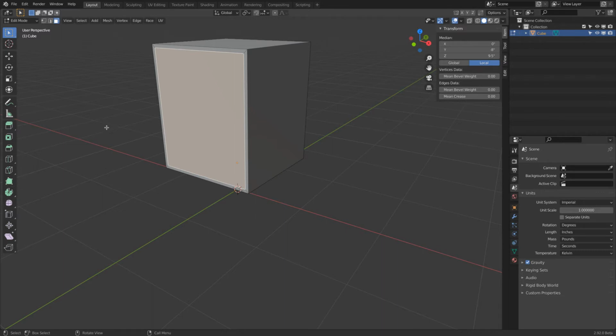Then we press K and I hold control. You see actually when I hold control, it snaps to the midpoint. Click, hold control and click to this midpoint and enter. Why did I do this? With holding control, snapping from midpoint to midpoint, very simple. This edge is now horizontal.